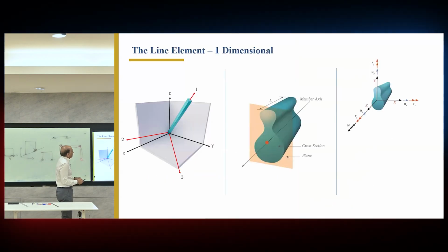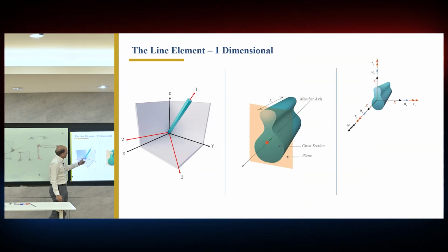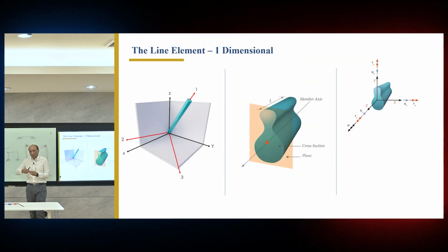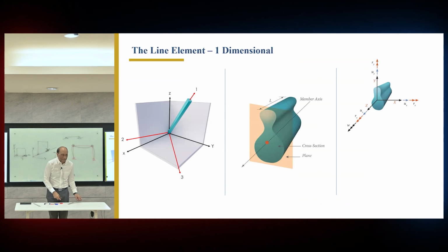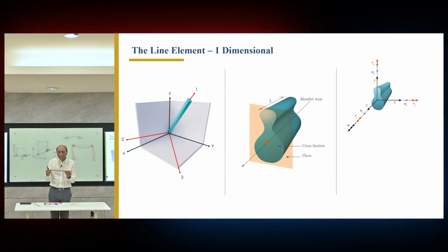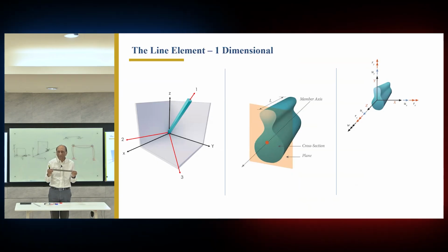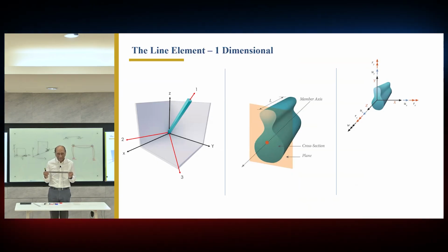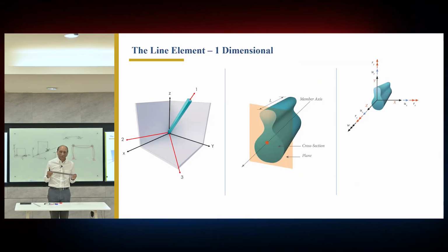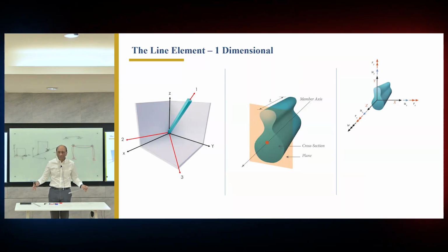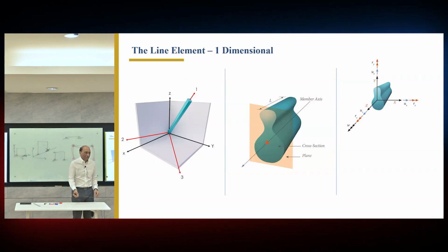Then we come to one-dimensional elements. We have seen these pictures in the last course. So a one-dimensional element is that the element is along any direction, only length. This is a one-dimensional element. Only length is a dimension. The other 2 are properties assigned to the line. So it's a one-dimensional element, but that doesn't mean it will live in one-dimensional space. Space is always 3-dimensional, but the element could be 0-dimensional or 1-dimensional like this one.